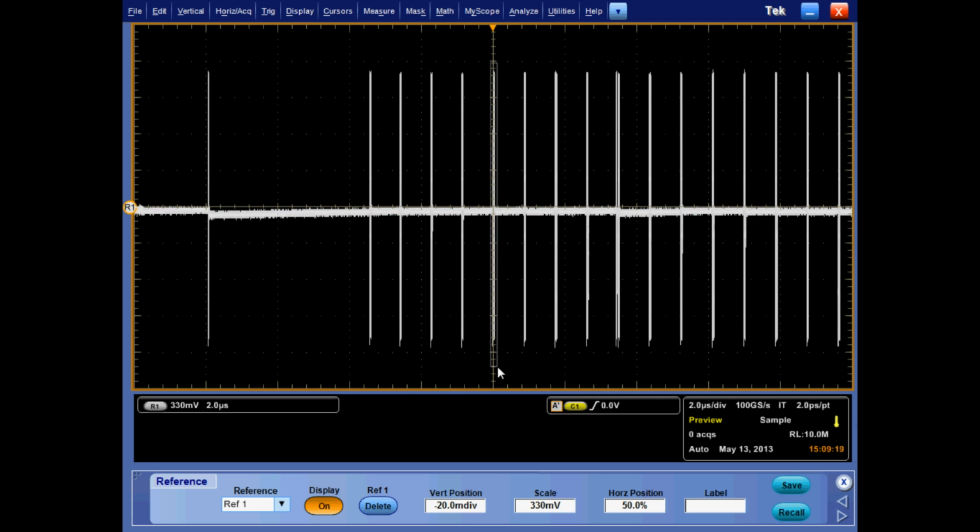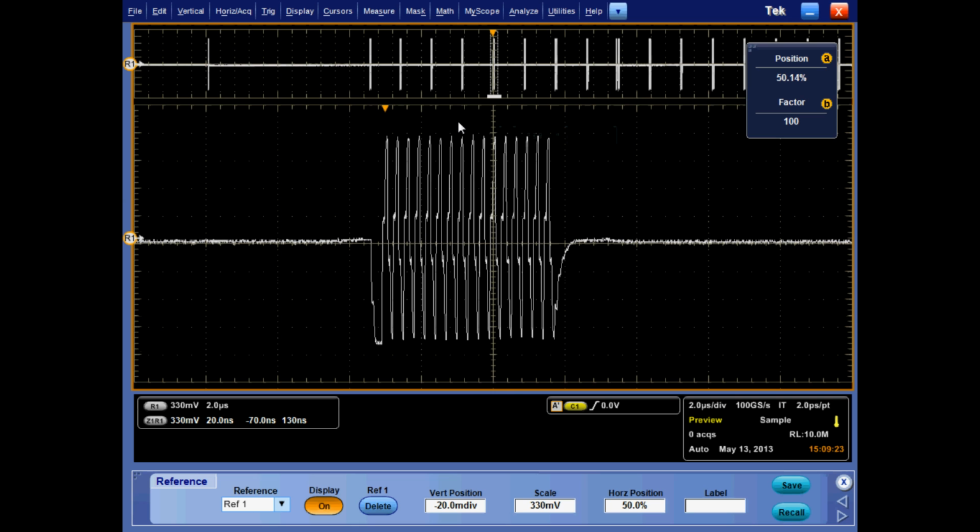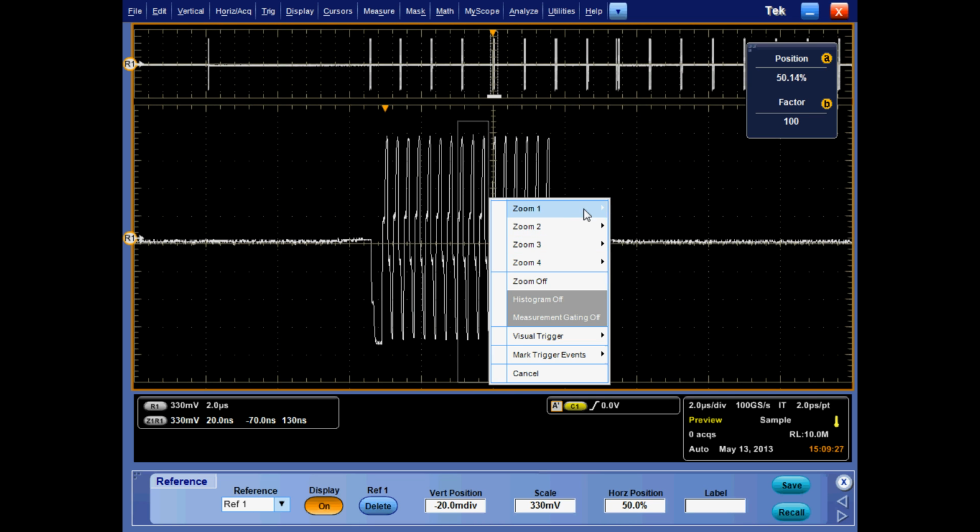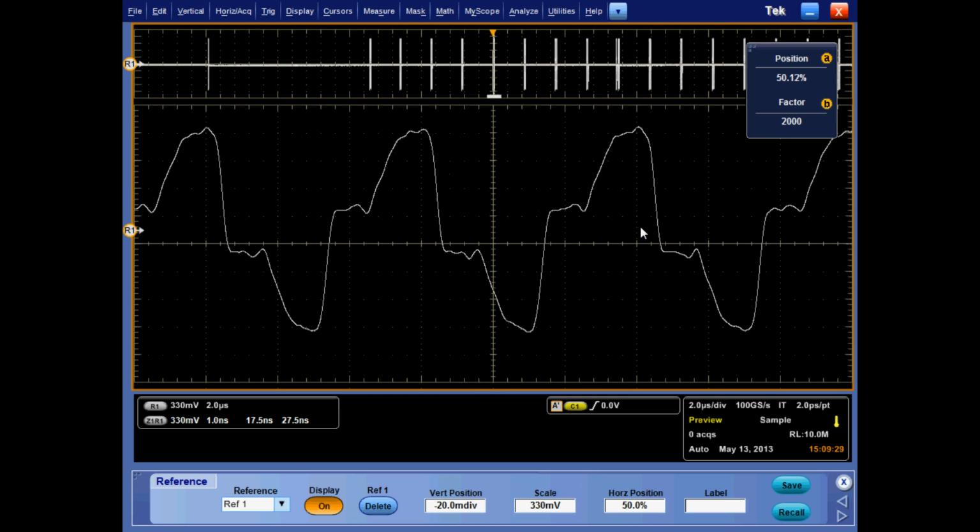As you can see, the waveform on the scope display contains reflections that are not caused by an impedance mismatch between the transmission line and the input impedance of the receiver. This is the result of the physical probing location, which is located away from the desired test point. In order to remove the reflections from the signal path, I must know the channel characteristics and receiver characteristics.